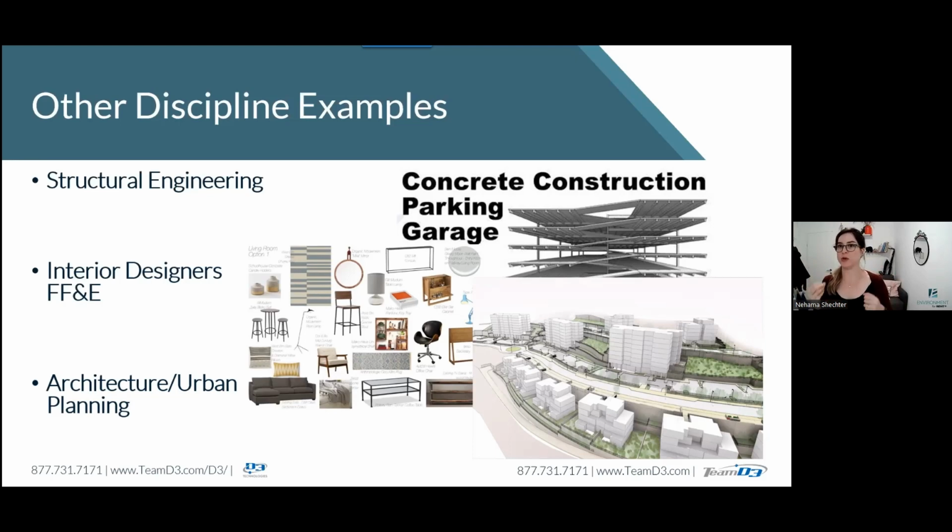The next step would be to incorporate it within the arrange wall feature. So you'll actually be able to insert parameters, and it would work with minimum and maximum height, because this feature is designed to read more complex surfaces, where on both sides of the wall you have different elevations. So it's designed to be able to read these 2 elevations and calculate what should be the end elevation. We're kind of considering how to move forward with this, but the nice thing about this tool is that a lot of times, even when we're not all the way ready, we will release some tool as a beta option, and we will just continue developing it.